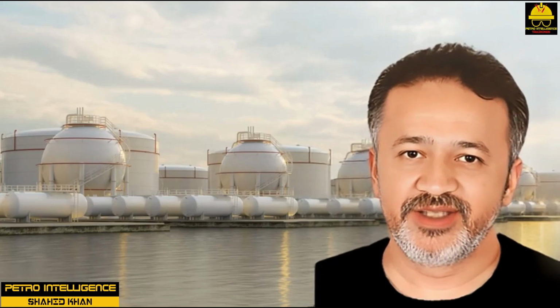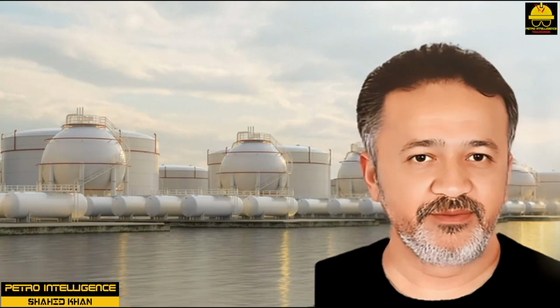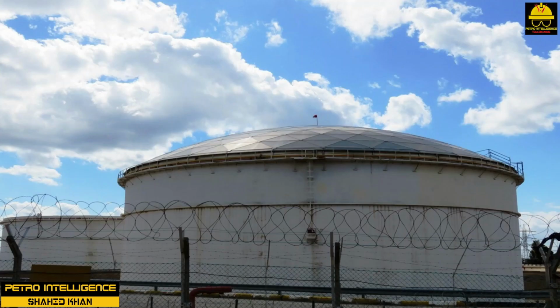Hemispheroid or dome tank, low to medium pressure. Hemispheroidal tanks can be classified as medium pressure tanks, 2.5 to 15 psig. This type of tank is typically used for the storage of higher volatility products. For this reason, hemispheroid tanks are a popular choice in the chemical processing industry.